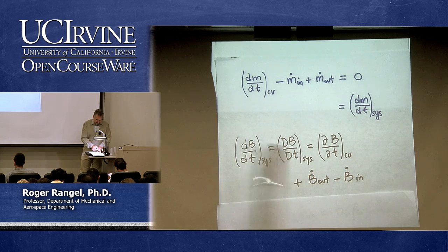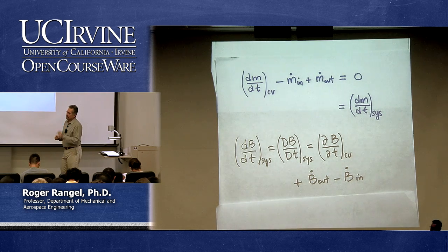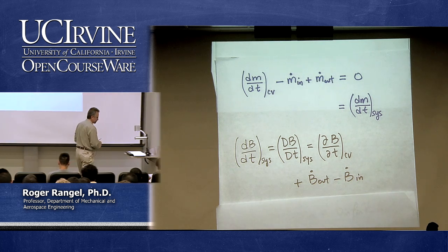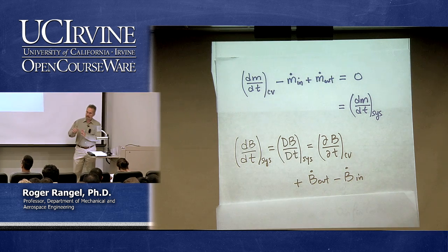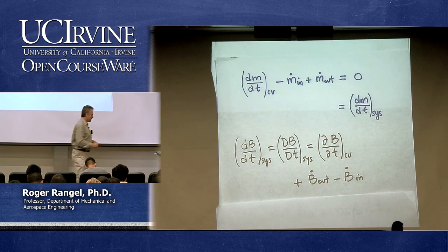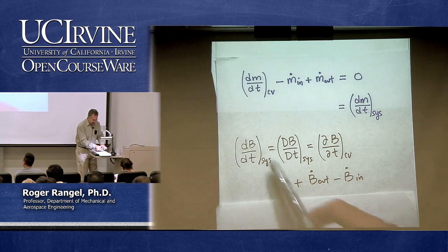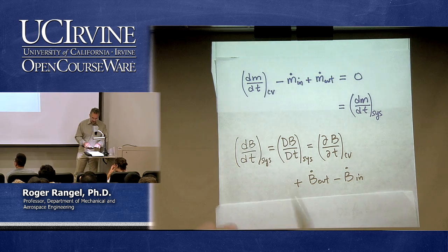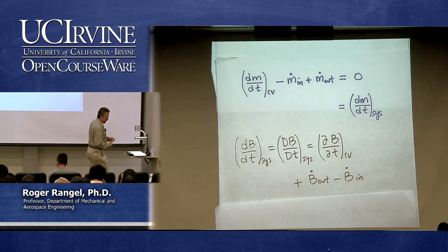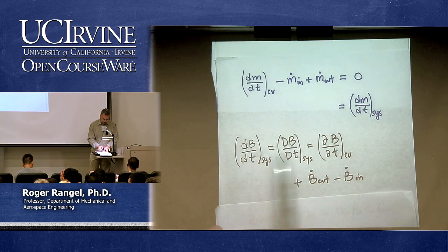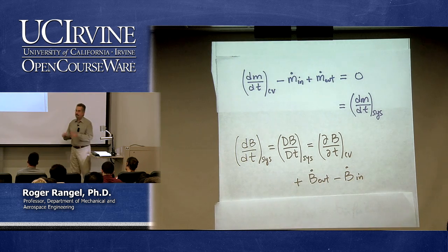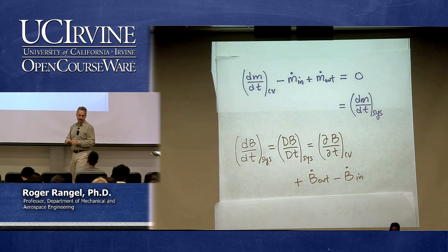The only other thing that I did here was to remind you of the use of this capital D. This is not the differential operator that we were talking about a moment ago. It was, remember, the way to remind ourselves that that's a derivative following the fluid. So whether you write it with a straight D or with a capital D doesn't really matter too much as long as you know what you're talking about. It's the system in both cases. So this equation right here is my simple Reynolds transport theorem.